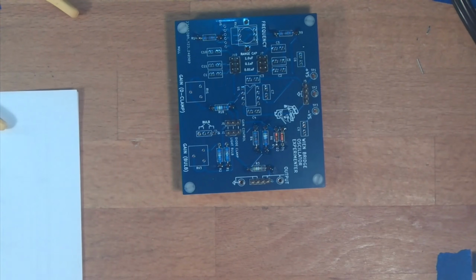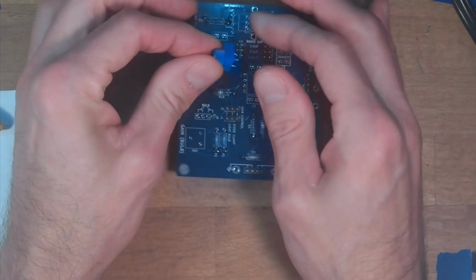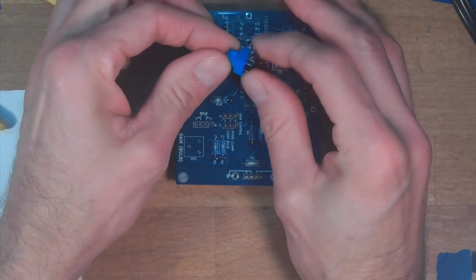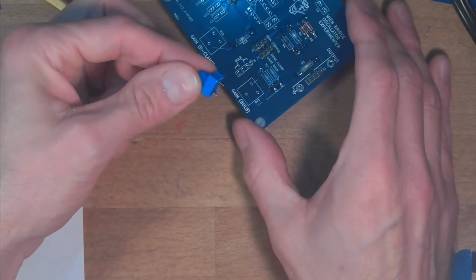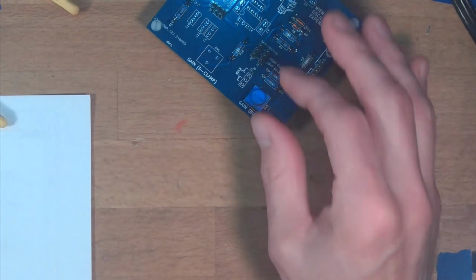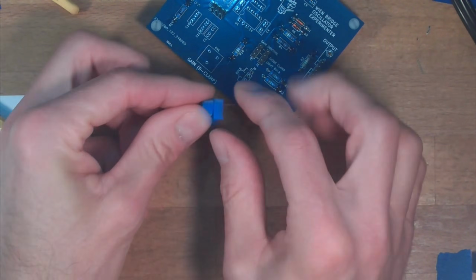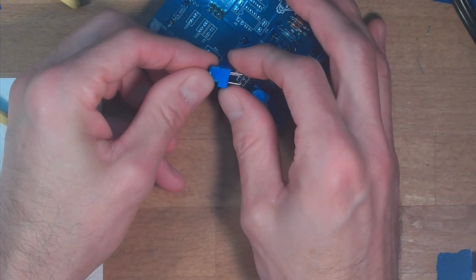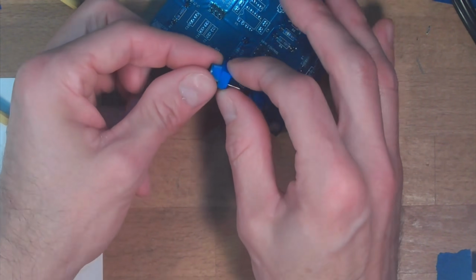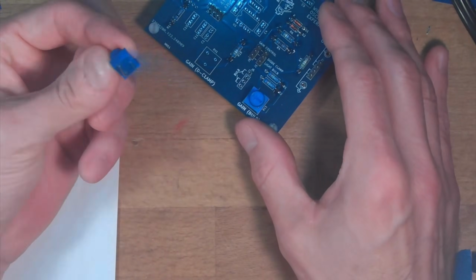All right, and then let's get our potentiometers in. Okay, so this should be a 1K potentiometer, and yeah, if we get it just right, 102. Okay, so that is our light bulb gain setting potentiometer. These are sort of tallish components, which gives us an advantage. We can flip the board over here. So let's see, that's 502. Yep, get that in there. So that's a 5K pot.